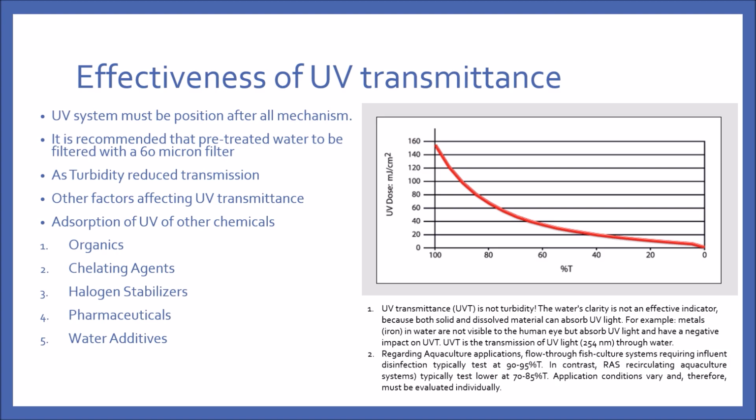One common problem we see in UV reactors is due to calcification. As you are running your RAS systems in saltwater condition, it is common for calcification to take place. Once calcification takes place in the UV lights, the UV is no longer reaching the pathogen effectively, hence reducing the transmittance value. In return, this reduces the actual UV dose that is used to kill the bacteria, rendering your UV ineffective.